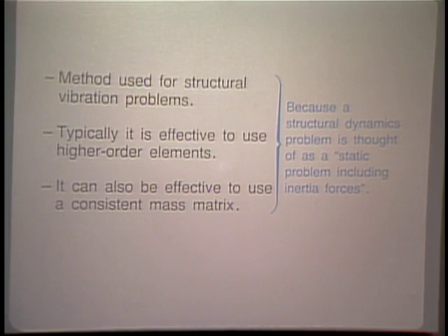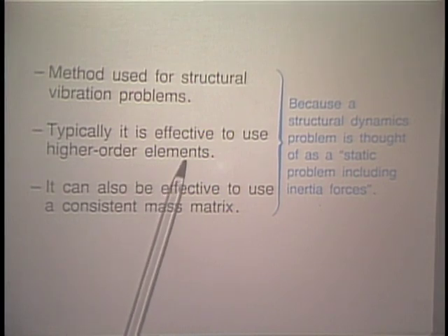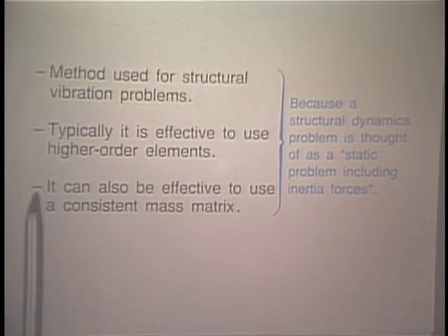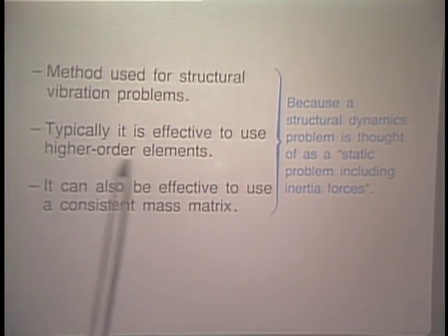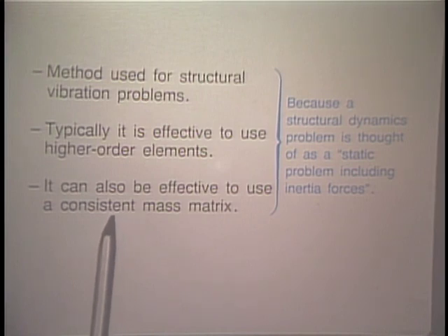As I said earlier already, the method is used primarily for structural vibration problems. It is quite effective, also using higher order elements. And if we do use higher order elements, we frequently find that the total solution should be performed most effectively using a consistent mass matrix.